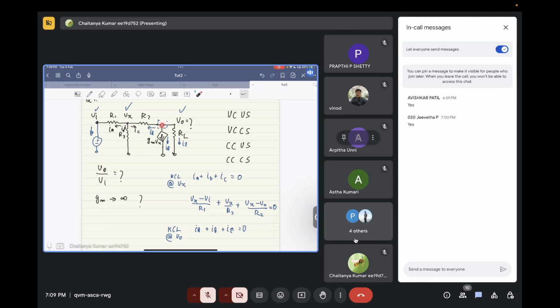From all the nodes when I'm writing the KCL, I am choosing the direction of the currents from those nodes to be in a single direction, so that all those currents amount to 0. Later you can manipulate it, but I find this more uniform.